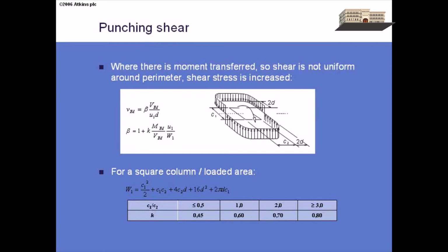In terms of the design of piles, we've been unsafe not considering this before. But the reality is, with a gamma C of 1.5 and various other gamma factors there, we've got away with it, but we haven't actually been achieving the sort of target reliability that the rest of the code achieves in punching design, things like that situation.